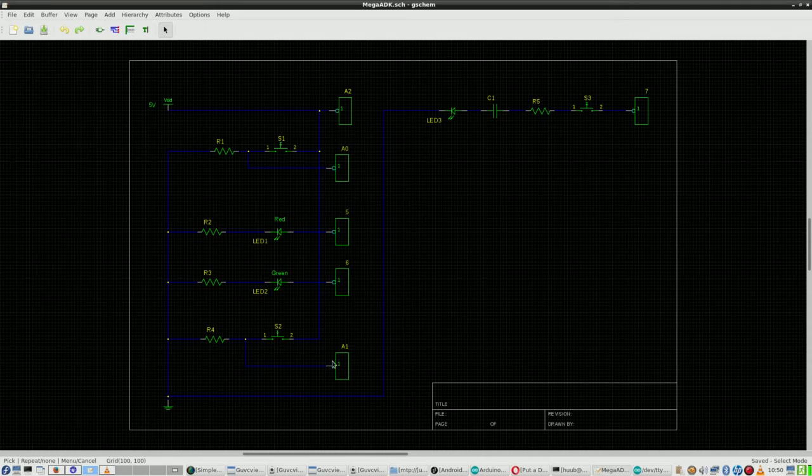Same thing for this button, connected to 5 volt and via resistor to ground, but also when it is made input to a 1, after which contact 6 is making sure that the green LED is going to burn, connected again with a resistor to ground.